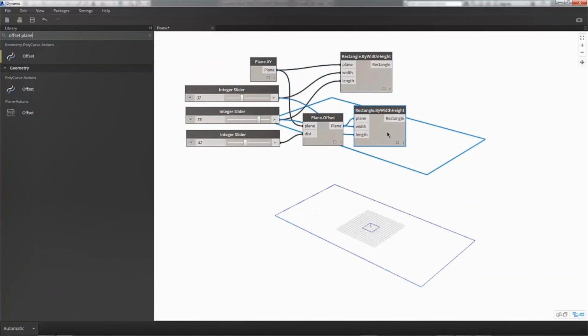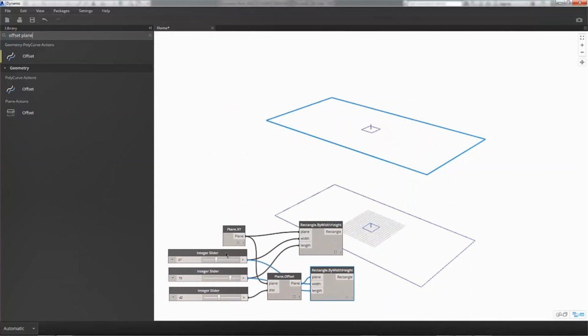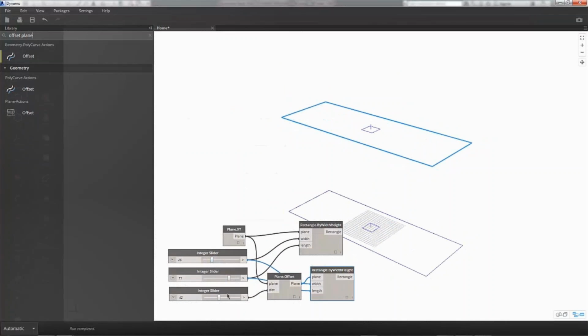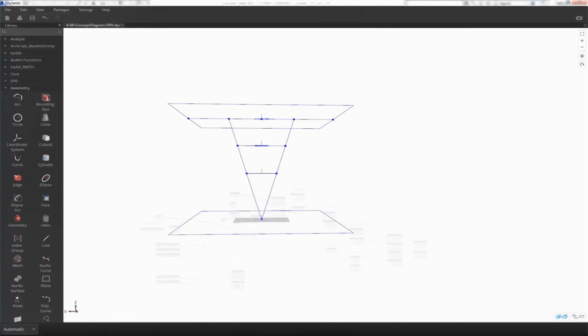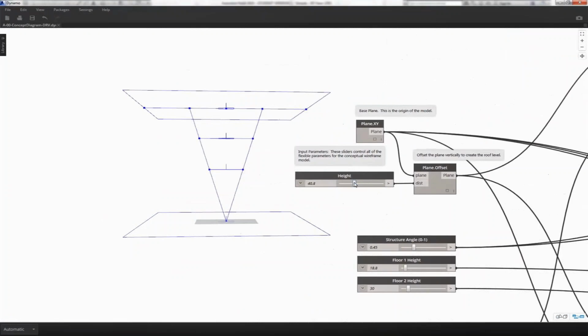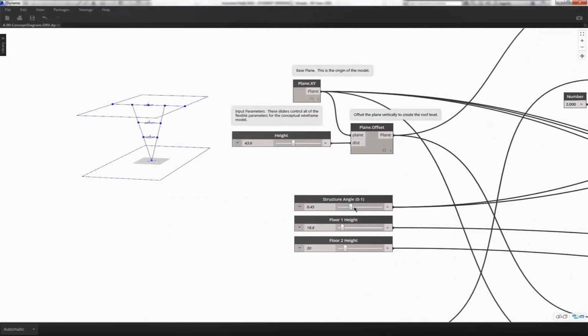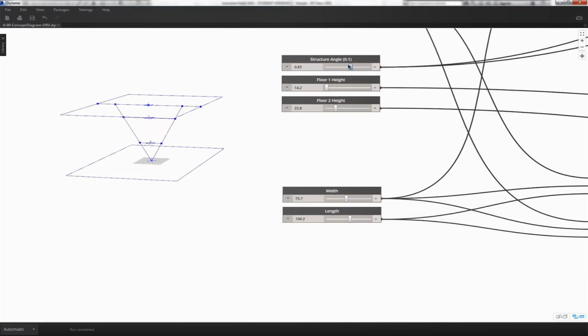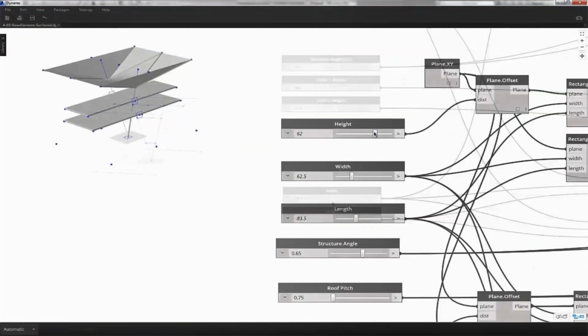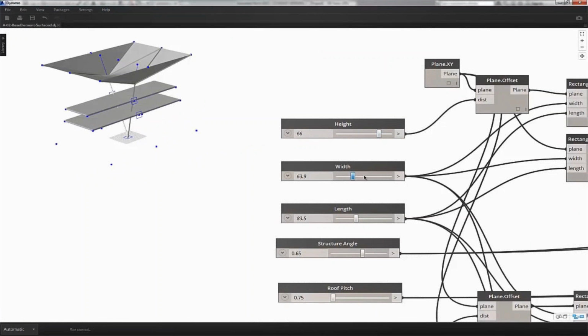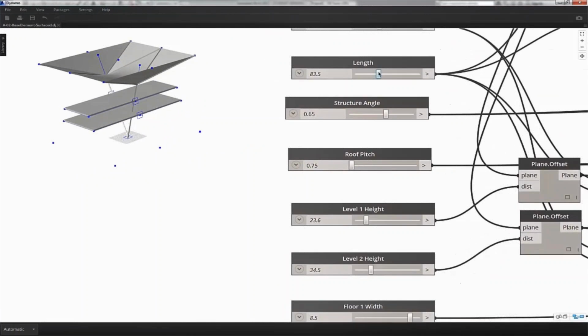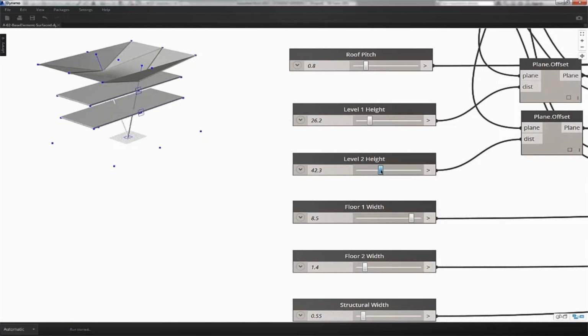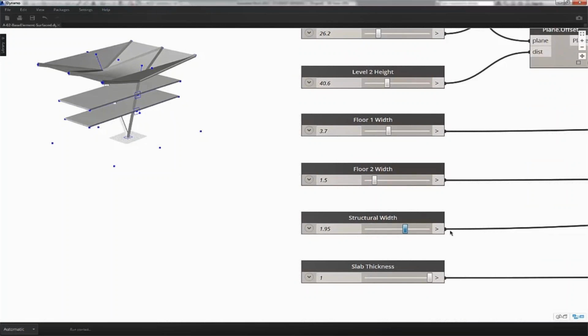So what you see here is the user using a node or a bunch of nodes that are visually controlled to achieve an optimal design for the length, width, and height. This could be done either with just a skeletal geometry, just a wireframe, or with the actual components. So the units you see on the screen are basically generic units. It's not feet or inches, but when they translate into Revit, then they become feet and inches.